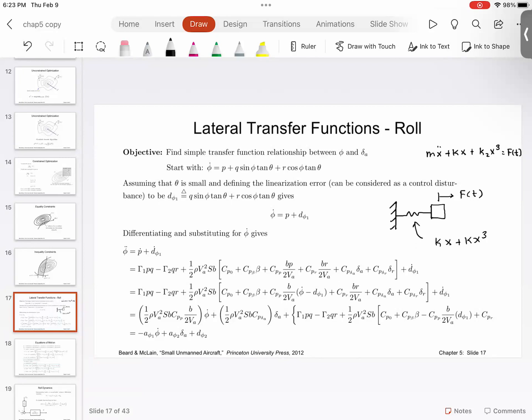What is the practical application? Imagine you have a suspension with zero damping, so basically it's a mass and spring. What is the meaning of asymptotically stable? Asymptotically stable means the eigenvalues have real part less than 0, and the motion decays after some time. The eigenvalues are on the left-hand side of the plane, not on the imaginary axis. Is everyone okay with asymptotic stability?